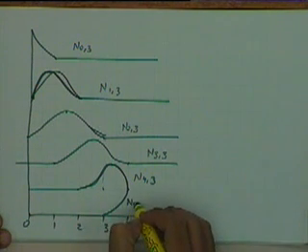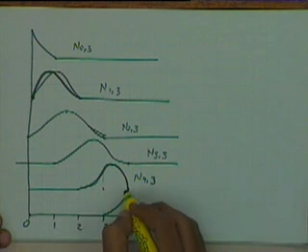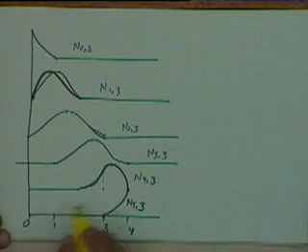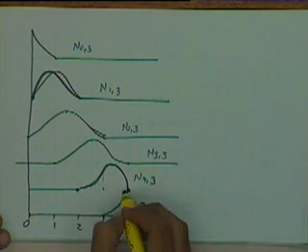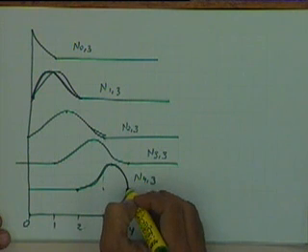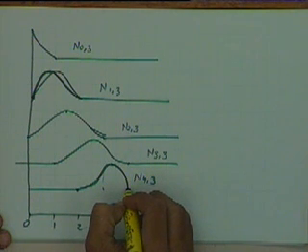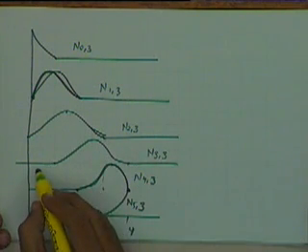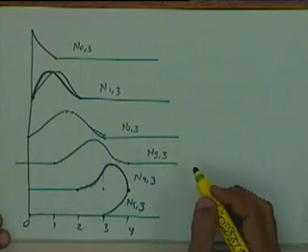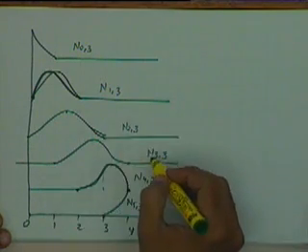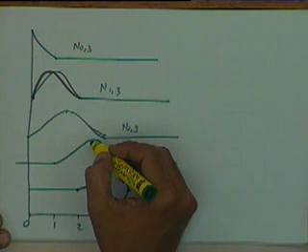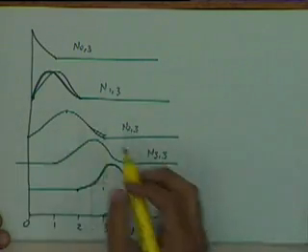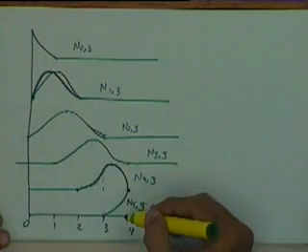This is n53. N53 is a quadratic function between these 2 points, 0 before this. N43 is a quadratic function between these 2 points. It's one quadratic function here, second quadratic function here, and is 0 before this. And n33 is also a set of quadratic functions, but it is symmetrical about the center. N23 and n33 have the same shape. N13 and n43 are somewhat similar but mirror images. And n03 and n53 are also similar.